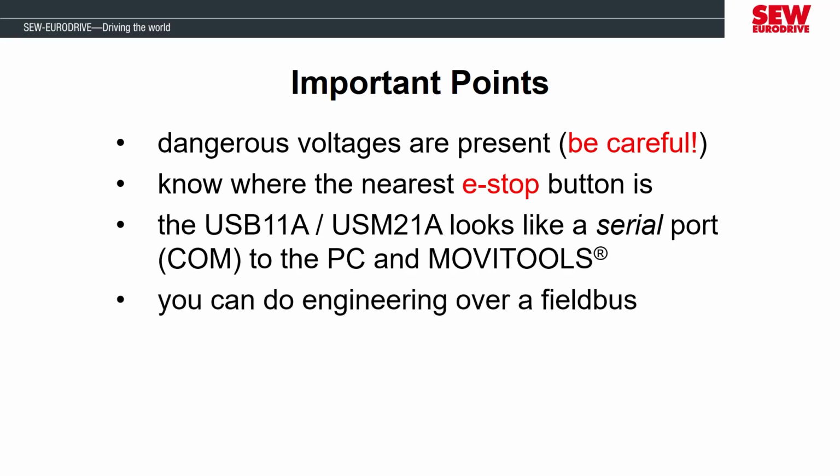An alternative to the USB cable is to use an Ethernet cable from your PC to connect to the MOVIDRIVE. The MOVIDRIVE will need an Ethernet-capable option card to have this ability, but it's possible to engineer the MOVIDRIVE over the network, and I'll be showing you how to set that up.